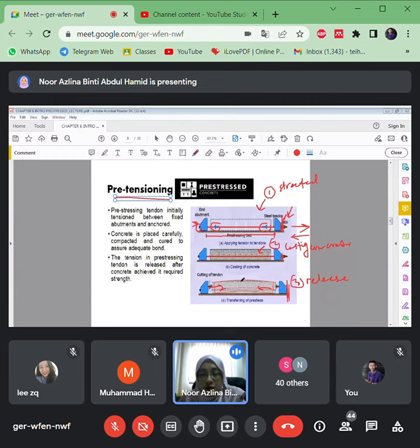That means we apply the loads, we tighten, we compress the reinforced concrete. So that makes a slight deformation here, which we couldn't see roughly, but there will be a slight deformation upward. Then after that, during its service, once the loads are applied here, it becomes a flat surface. So that means there's no downward deformation that can induce cracks in the concrete.